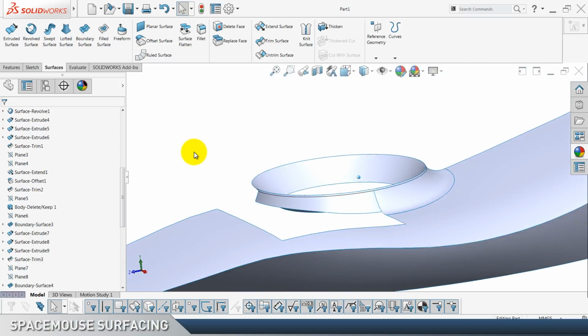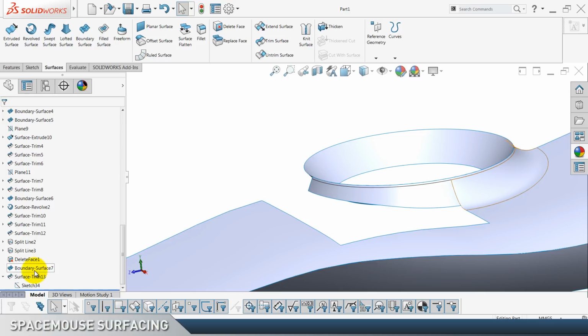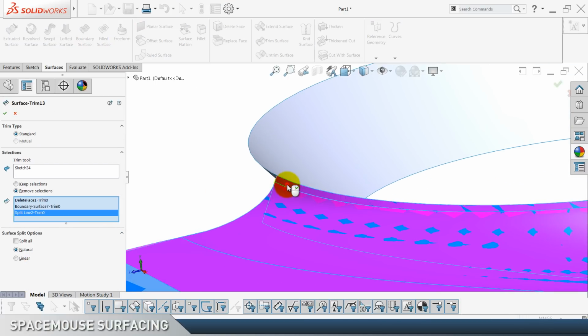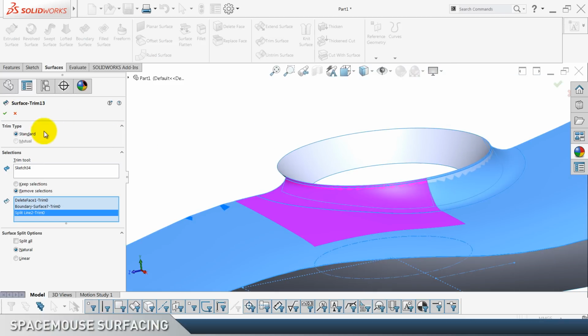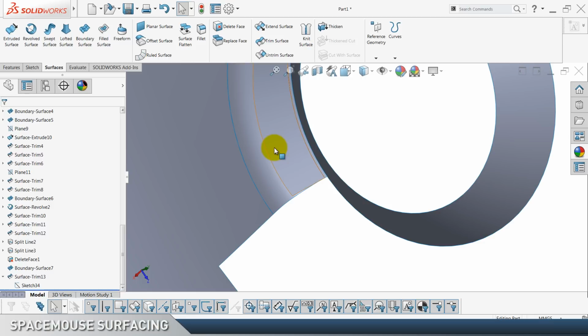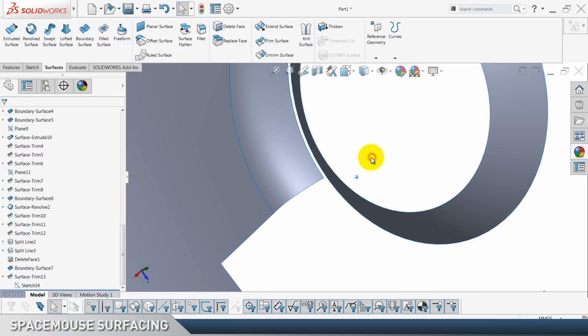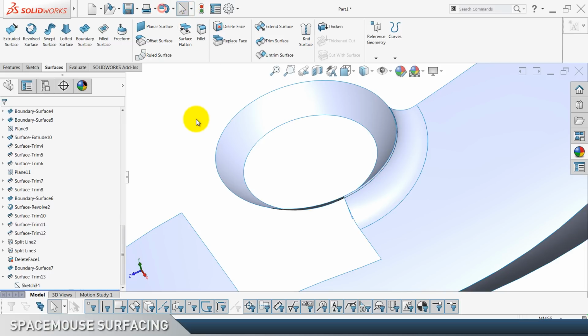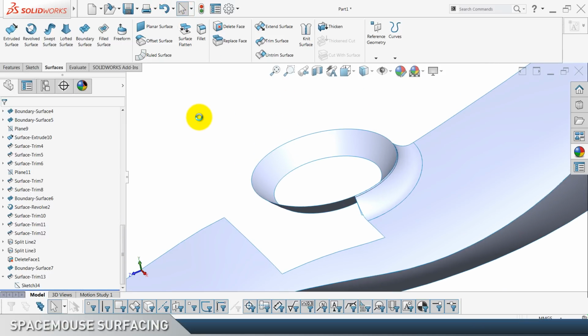And what is also wrong with this trim we did is that we actually had to remove this one as well. Click OK, and we can now hide this face that is left. We don't need it, or we do. Okay, bring it back.